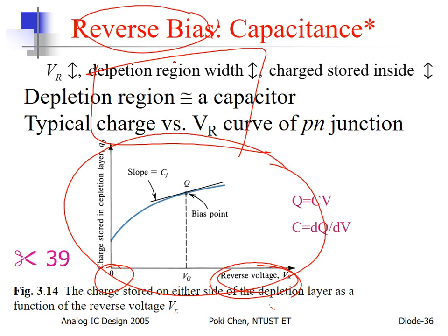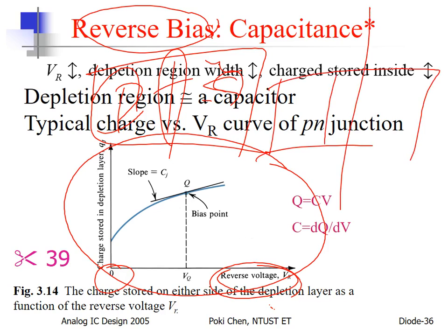as I told you, when p-type and n-type meet each other, it is very easy for each side to diffuse to the other. But after equilibrium, it becomes harder to diffuse to the other side. If you increase the reverse bias, the depletion region will become even wider. It means much fewer charges can be pushed to the other side.